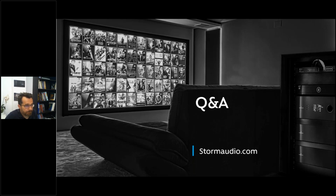Last questions. Yeah, it's similar to that. What we experienced is that if you have two front subwoofers, LCR speakers capable, you can already have a very well controlled bass. Especially if you also use your other speakers to play at least between 70 Hz to 150 Hz, you will have a good control. But if you can add more subwoofers to them, that can really bring an even better control.